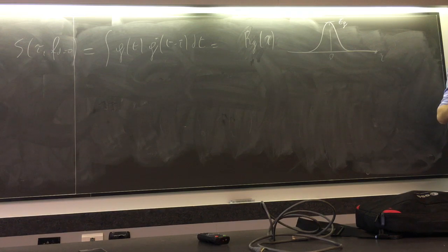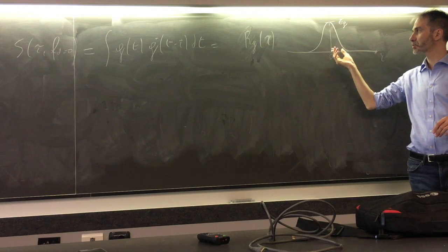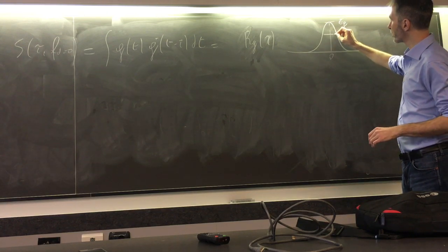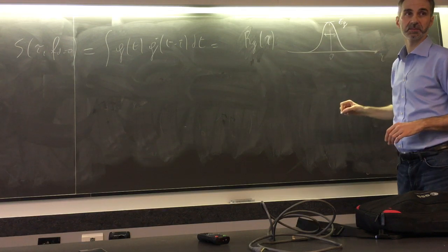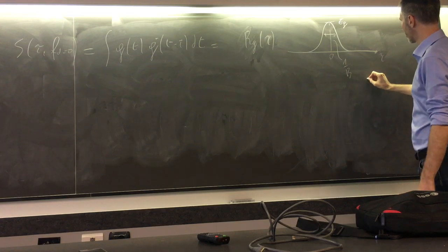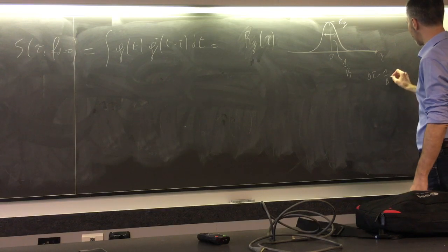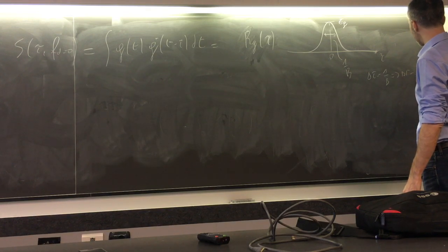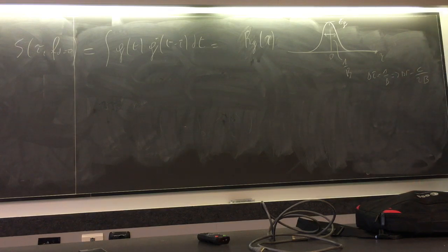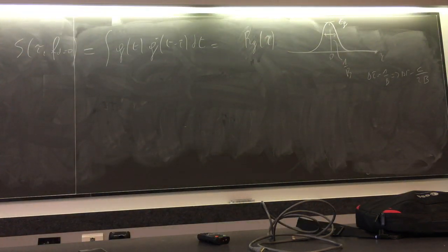So, this tells us that your time resolution depends on how wide this peak is, and this is more or less the inverse of your bandwidth. So your resolution about tau is 1 over the bandwidth, hence your range resolution is half the speed of light divided by the bandwidth. We saw this already. So now let's do the same for the other section.